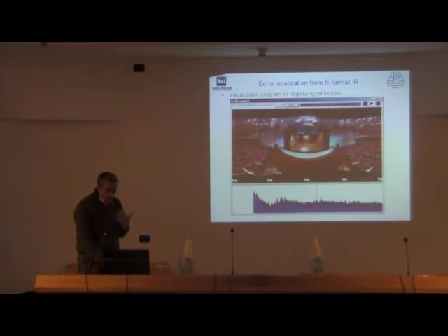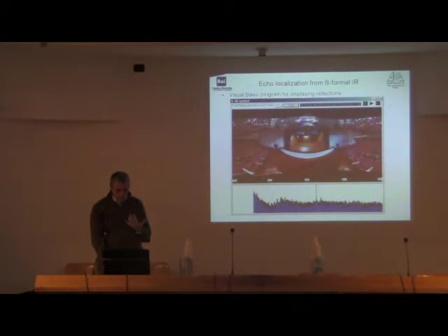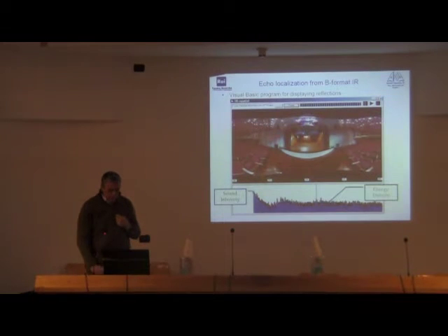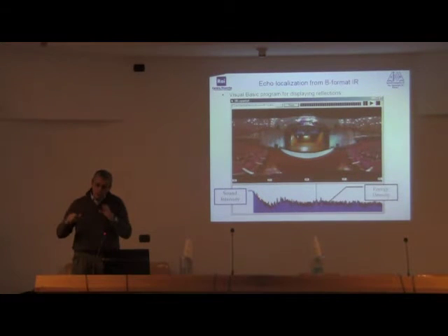Here we are in a concert hall in Patras in Greece, and we measured the impulse response. You see the impulse response here below. There are two curves. In blue, you see the sound intensity, and in gray, you see the energy density. When the sound intensity is close to the energy density, the sound field is very active. When the sound intensity is low compared to the energy density, it means that the sound field is very reactive. The sound is diffuse, and there is not a lot of energy traveling in a precise direction.